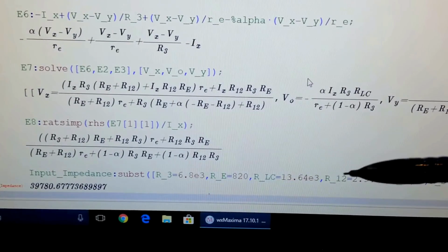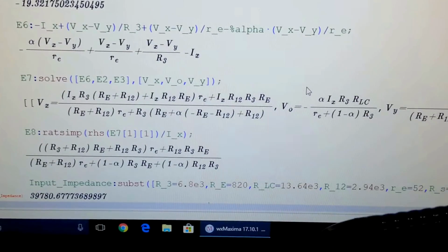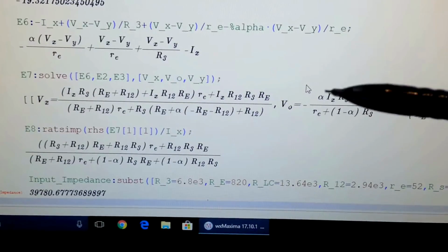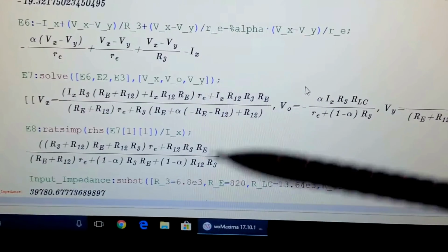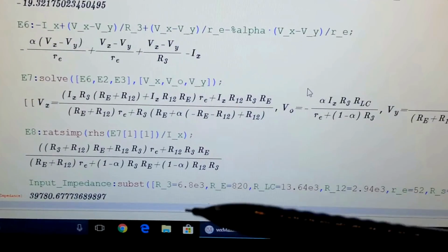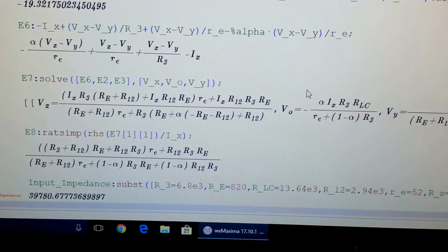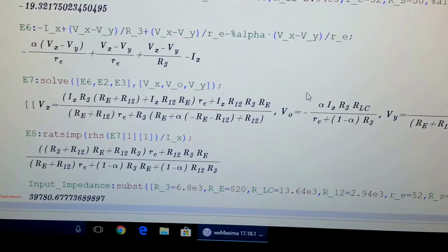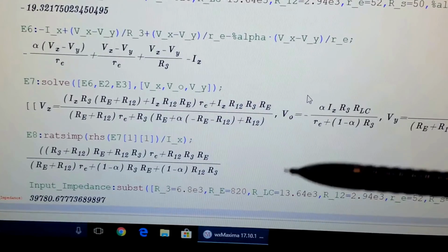Normally, you don't use positive feedback in circuits because it tends to create oscillations, because the feedback that you're using is in phase with the input. So if you want to create a good oscillator, then you normally use positive feedback. But in this case, the positive feedback works to our advantage.